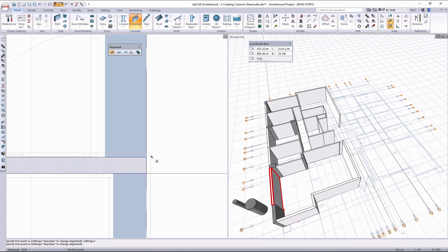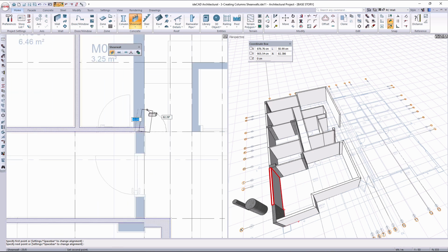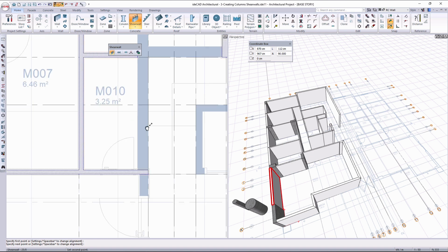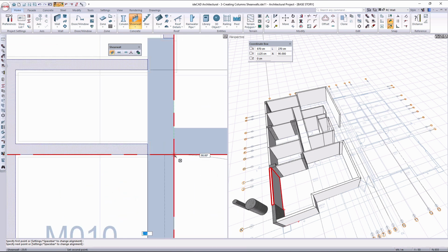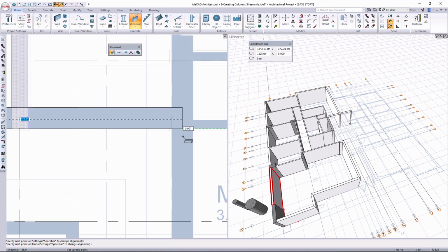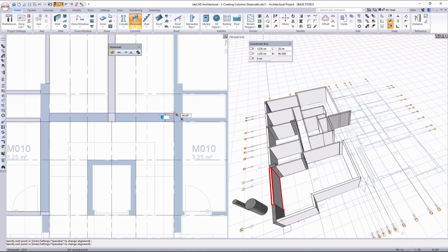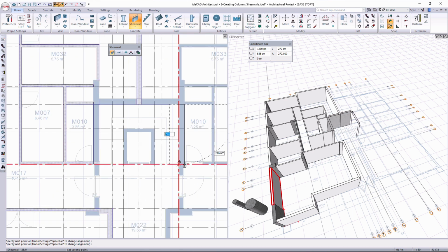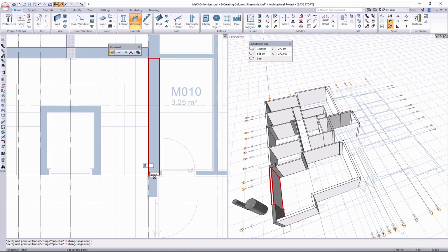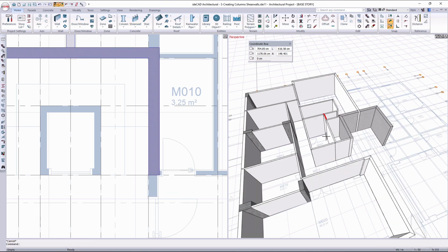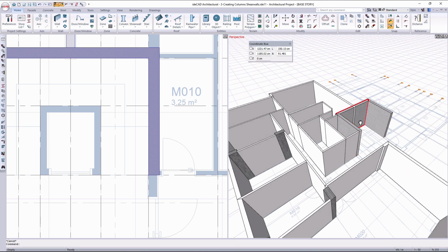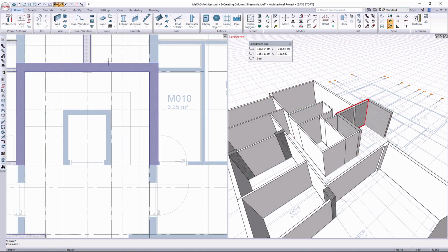Shear wall drawing is quite similar to wall drawing. You start by clicking a point, then define the direction in which the shear wall will extend, and complete the drawing. You can use the Delta command on the toolbar or simply press the spacebar on your keyboard. If needed, you can later reopen the settings dialog to adjust parameters like elevation levels or other properties.